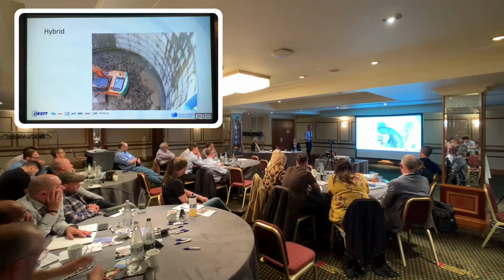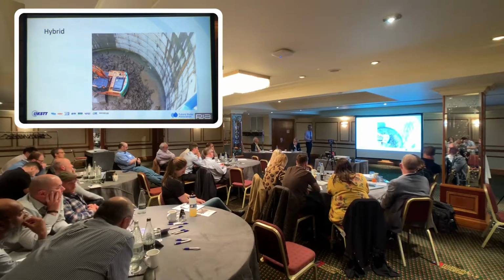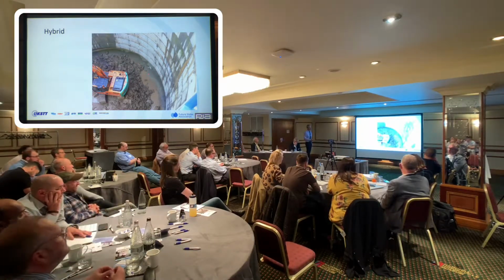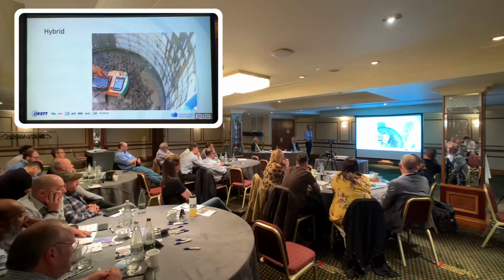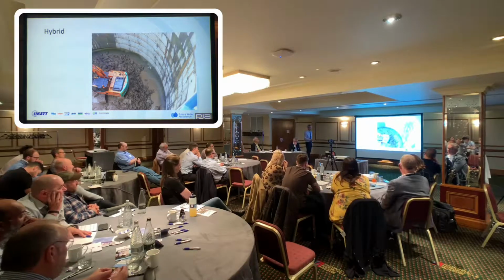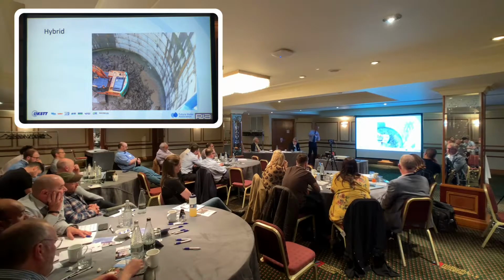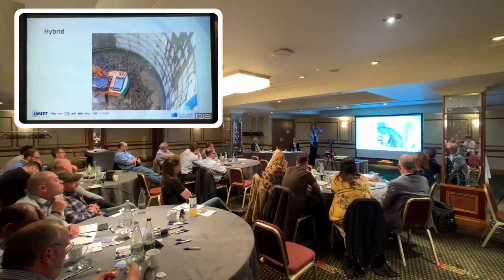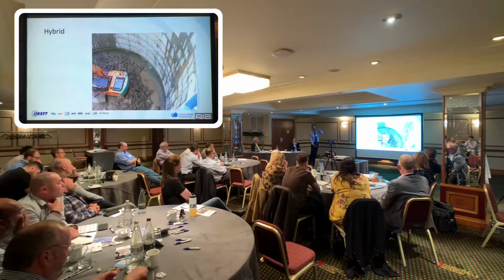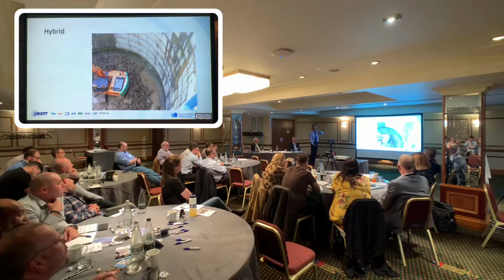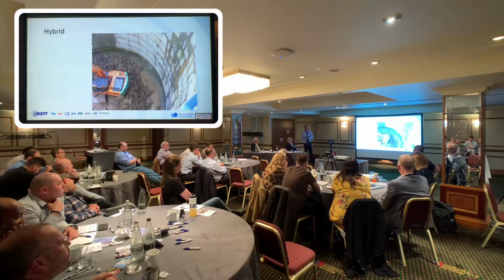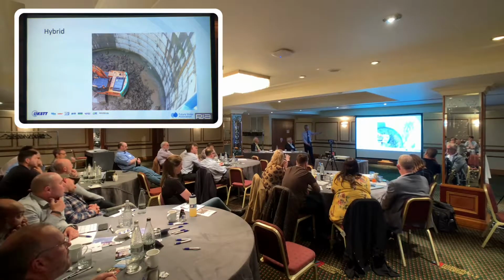In this particular instance, this is a project near the Wirral, and we had artesian water beneath the base. So taking the base plug very deep reduced the clay that was beneath the slab, and the dewatering that was needed to reduce the artesian water pressure in the temporary state to prevent that base from blowing was far worse than it would be if we thinned the base.